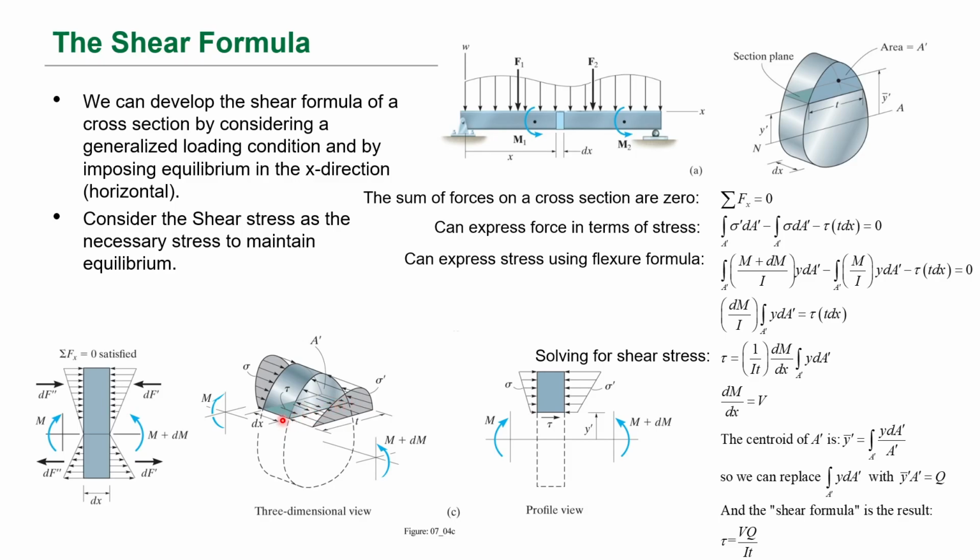Okay. It has thickness dx, and it has stress on the back surface of sigma, sigma prime on the front surface, moment on the back surface of M, moment on the front surface of M plus dM. Okay, and then what we can do is take that slice and look at that shear force and find out if we can express this shear force in terms of these stresses and moments. Okay, so that's what we do here.